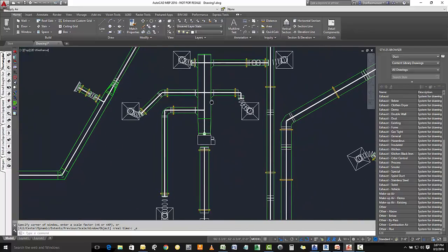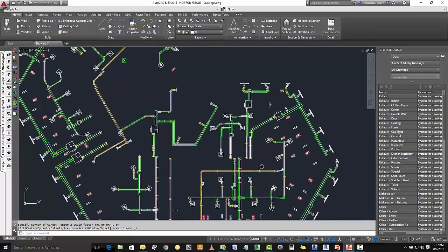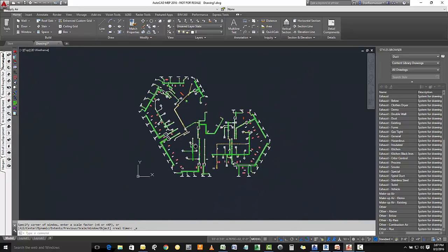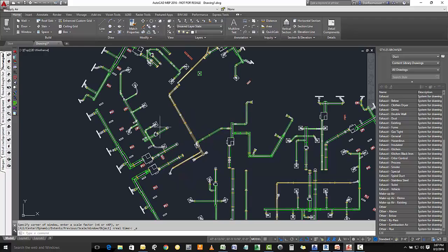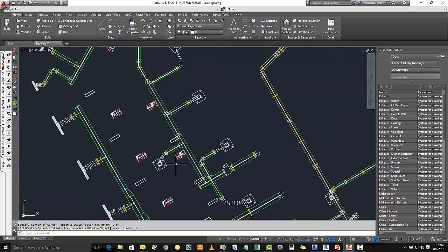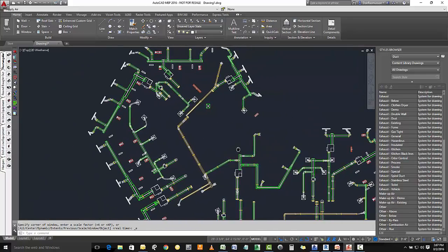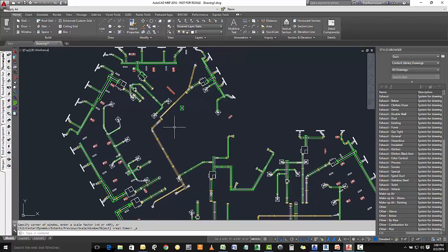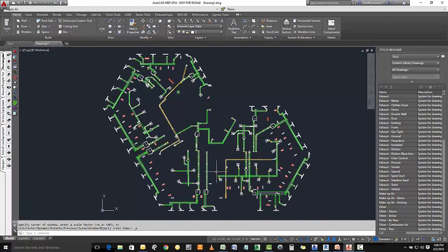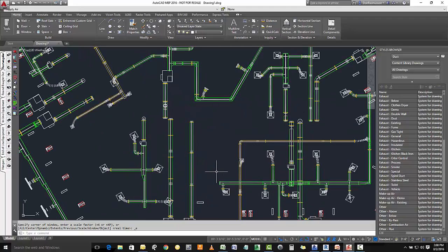One thing that is nice though is it does add your hangers for you based upon rules that you set up. So you see I have hangers populating here. I did not have any hangers inside of my Revit model. And for most of the parts we're doing pretty good. We can go ahead, and this is a usable file in the fabrication world. It's not perfect. We'll have to go through and do some coordination, if you will, because the fab parts have changed from the Revit parts, which may alter the design.